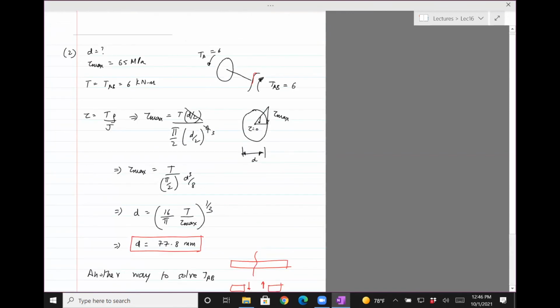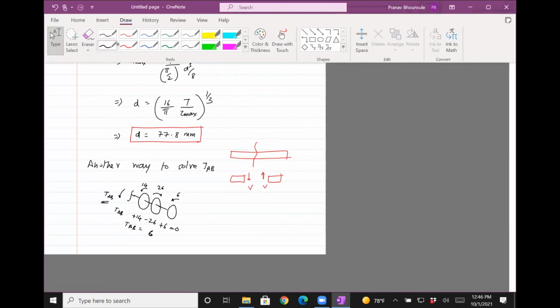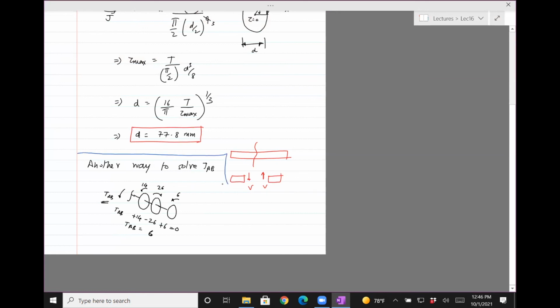But if you see the way I got it here, it's clockwise. And that's because if one side is acting counterclockwise, the other should act clockwise, so that when you join them together, the sum is equal to 0. So it's exactly the same: things which are true for free body diagrams are true for shafts subject to torsion.